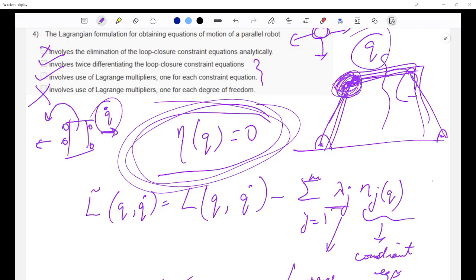If it is a wheeled mobile robot with a no-slip constraint, we cannot slip sideways, then it is non-holonomic. Because we have closed kinematic chains, these chains reduce the degrees of freedom of the robot. So holonomic constraints in parallel robots are geometric loop closure equations that restrict the positions of the joints so that the mechanism remains closed.